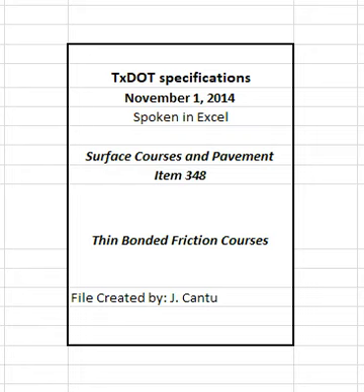4.4.2.1.10 Trial batch production equipment. Use only equipment and materials proposed for use on the project to produce the trial batch. Provide documentation to verify the calibration or accuracy of the asphalt mass flow meter to measure the binder content. Verify that the asphalt mass flow meter meets the requirements of 0.4% accuracy, when required, in accordance with Item 520, weighing and measuring equipment. The engineer may require that the accuracy of the mass flow meter be verified based on quantities used.